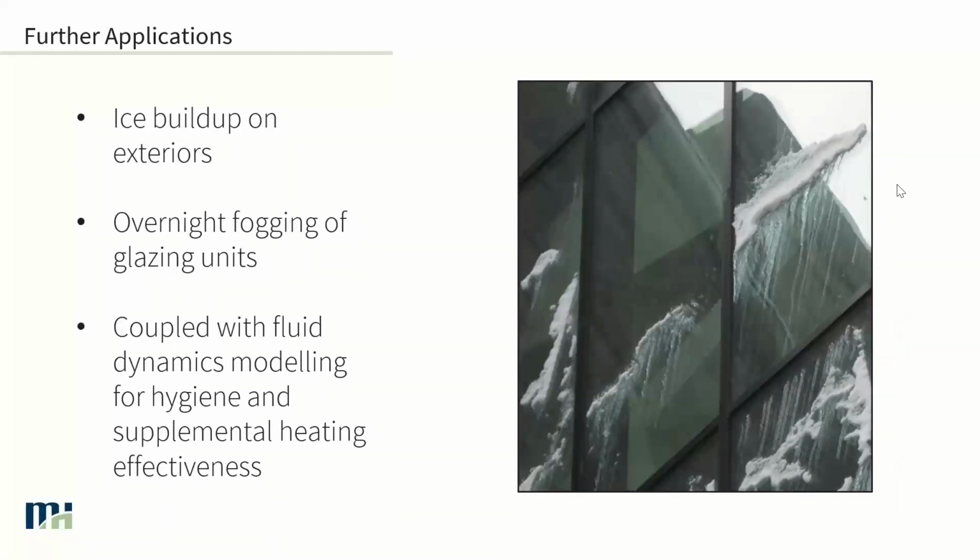So really the idea of using thermal modeling, 3D modeling, when we can, to assess surface temperatures can be quite useful on a whole slew of applications, right? It's not just for condensation resistance. We could be looking at exterior temperatures as well. If you're looking at certain locations where there's concern for ice buildup on the exterior, we try to make windows as energy efficient as we can now, but is that decreasing temperatures on the outside so that nothing is heated up enough to melt ice on the exterior side, and it builds up, and where it can potentially slide off once temperatures become a little bit warmer? So these types of analyses can be used to assess that risk as well.